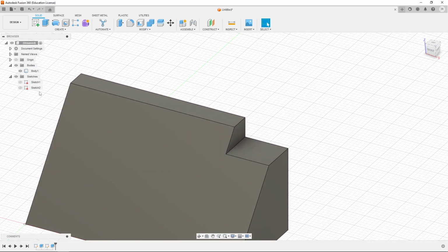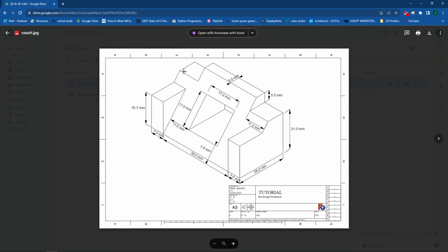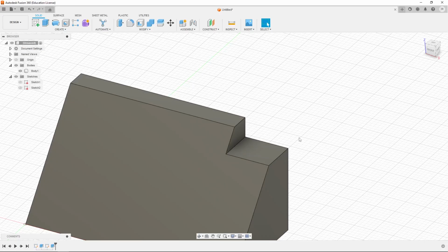Now, notice that this second sketch is gone. So now we have a lot of options because based on our drawing, we want to do the same thing on this side. What should we do? Should we create another sketch of the back face, same measurements, cut out that corner? That's one option. We could also potentially mirror things, and that's actually another thing we can try. And mirroring is even more complicated because we can do it in a sketch or outside of a sketch. There's a lot of options for this.